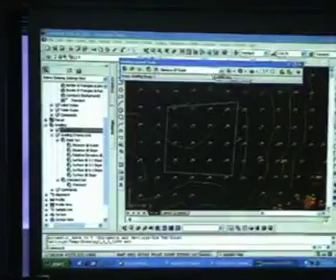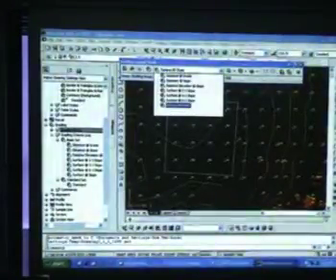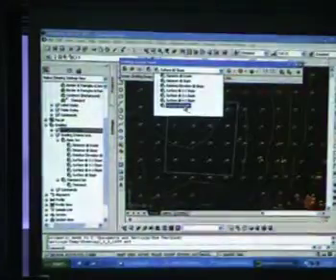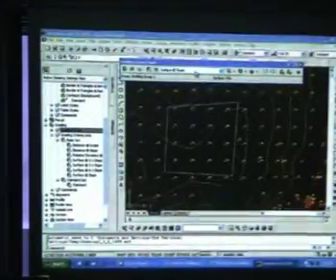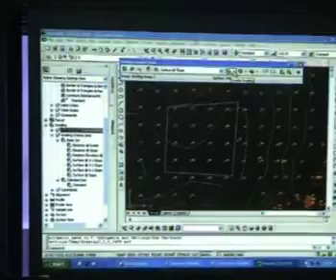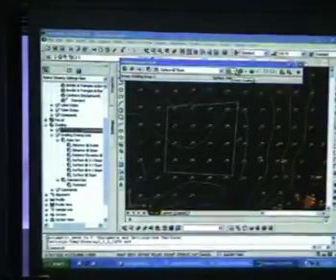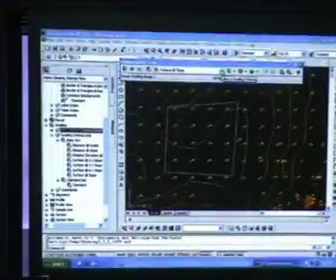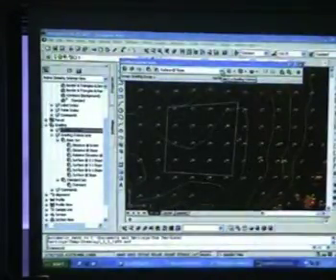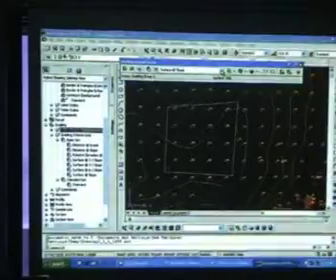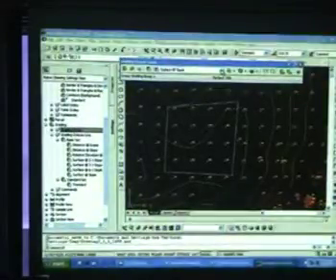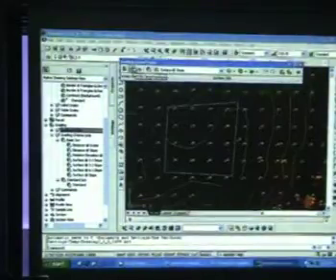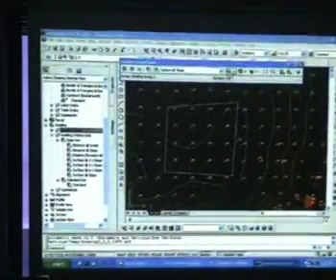Once you switch to basic set, you'll find this drop down list is exactly the same as what's in your settings. So I'm going to set this at surface at slope. Now we go to the next icon. Slope surface at 2 to 1 slope, right? That means the slope value is the slope gradient. This is quite good in the sense that it's quite easy. You just go from one icon to the next.